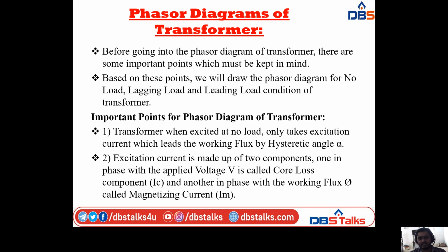Those important points are: the first one is, a transformer when excited at no load only takes excitation current, which leads the working flux by hysteresis angle alpha. Transformer when excited at no load only takes excitation current, which leads the working flux by hysteresis angle alpha.